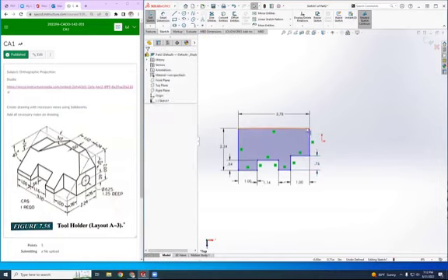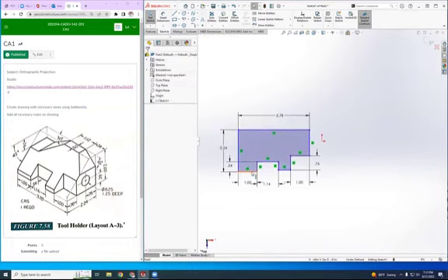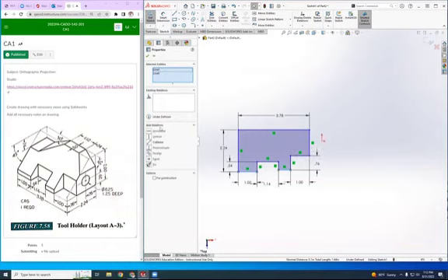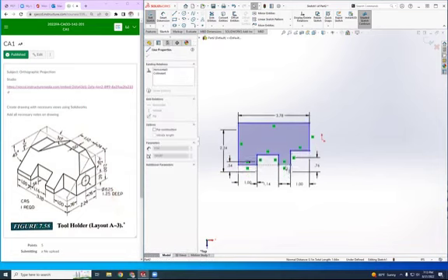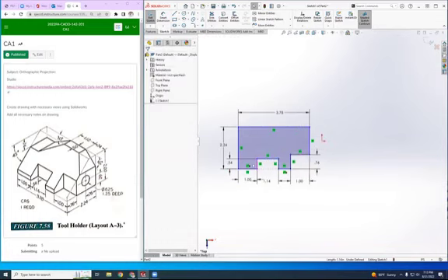Yeah. Now notice that this shape can still be skewed, and you want to check this before you do anything else. This line and this line should be aligned. They're aligned. So I'm going to hold the control key, select this line, and select this other line, and that is going to bring my geometric constraints or relations. And I'm going to say they need to be collinear. Collinear. And now they cannot be moved. Or if one of them is moved because it has a collinear constraint, the other one's going to move with it. You do not want this one to be collinear constrained with this one because this one's 0.76 and this one's 0.54.